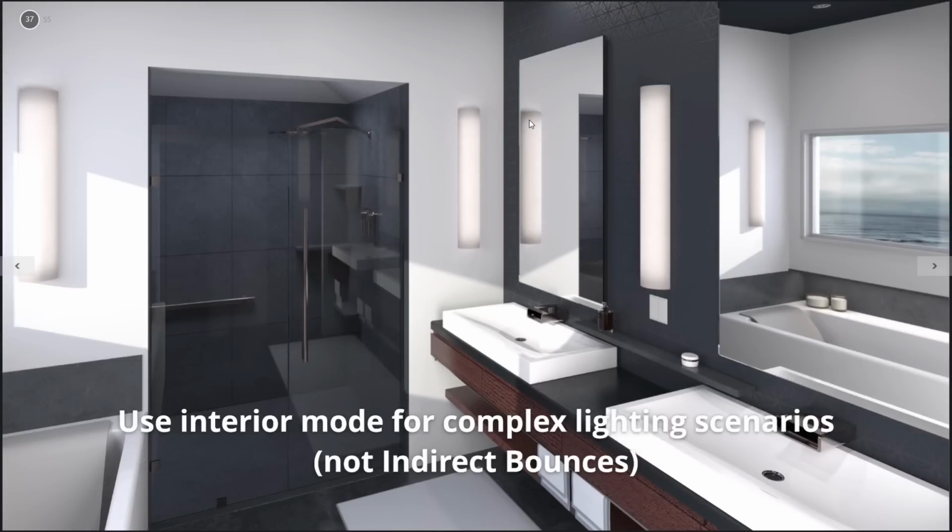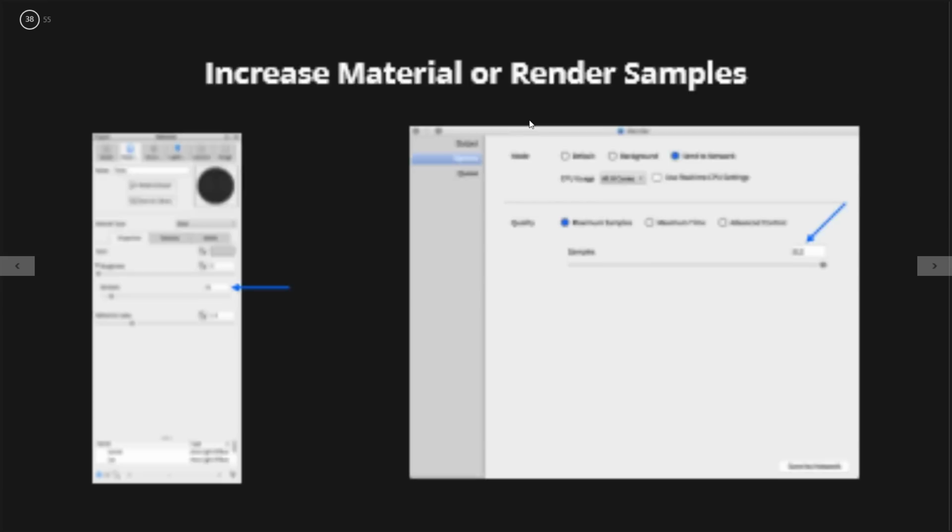Also, use interior mode when you start getting those white hotspots. Don't rely on indirect bounces. For those of you who are hoping to get these kind of high quality results out of KeyShot 5 or even 4, KeyShot 6 has been out for a year and it's got interior mode, and it's meant for doing these types of images. So if you're getting little white hotspots, use interior mode in KeyShot 6.